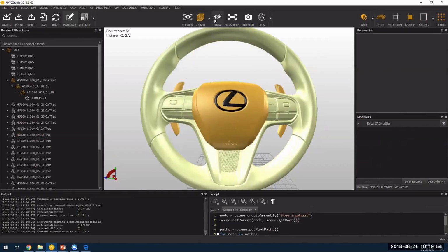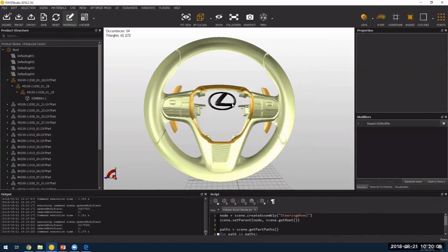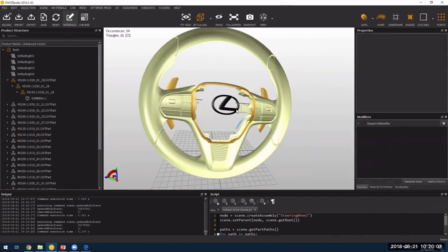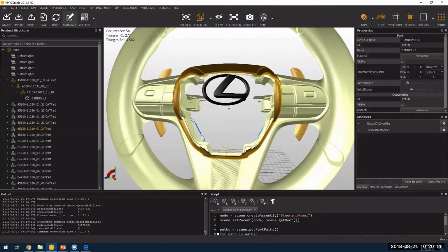Here, my viewer displays double-sided mode, but it will not be the case in Unity. So let's toggle on the one-sided view, also called the backface culling mode in 3D applications. And we can see that some faces are flipped. They are not facing the right direction. For example, my centerpiece here is just upside down.